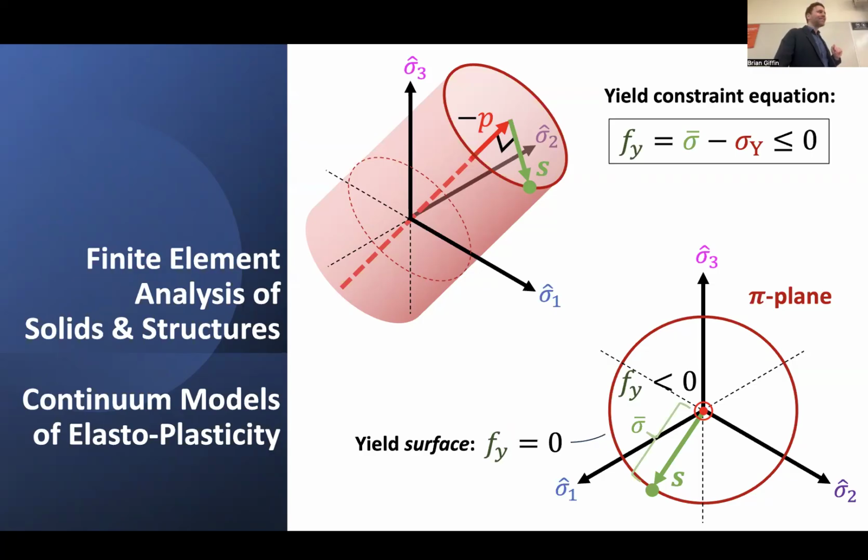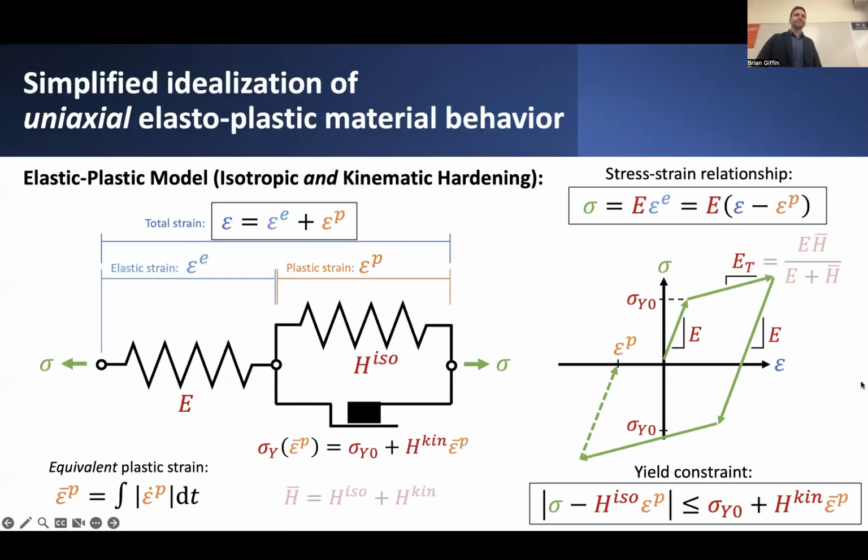But before we dive into some of the details and rationalize how exactly we get there, let's recall what we developed in the previous lecture on the subject of these simple one-dimensional representations of elastoplastic material behavior. If you remember, we proposed to develop some kind of component-based model, an idealization of elastoplastic material behavior, which we could construct by taking some springs and some frictional sliders, these one-dimensional elements. We could pattern them together in this kind of assembly.